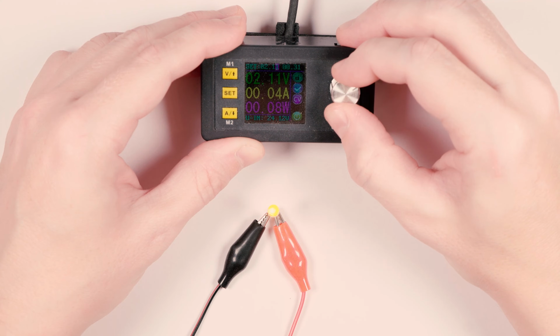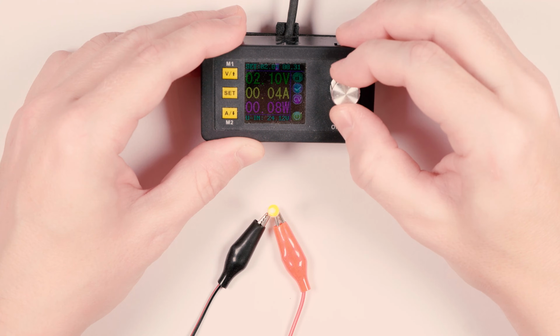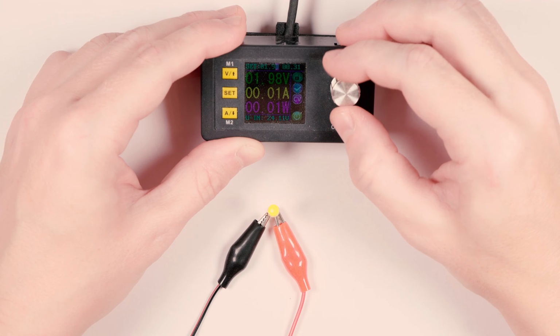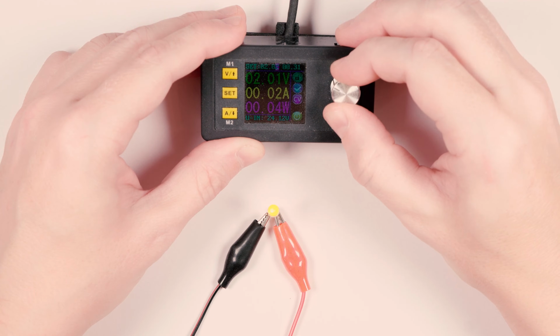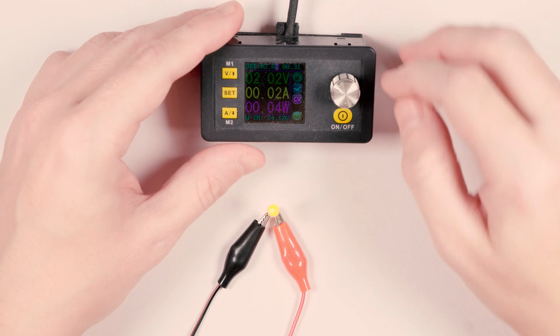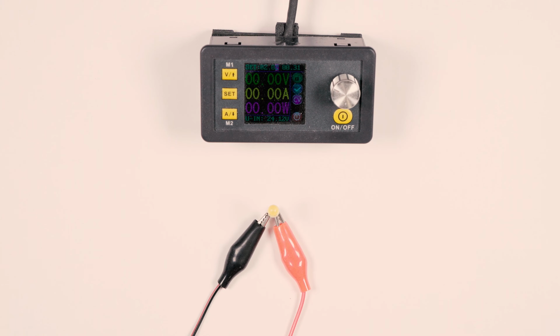What conclusions can be drawn from this experiment? Of course, each LED does have a voltage at which it operates. But this voltage is very difficult to find, since it is within very small limits. If you lower it, the brightness drops sharply. If you raise it, the current rapidly increases and the LED may fail. Meanwhile, you probably noticed that the higher the current, the higher the brightness. It turns out that when powering an LED, it is more convenient to rely on current rather than voltage, because in this case, we do not have to stabilize it so carefully.